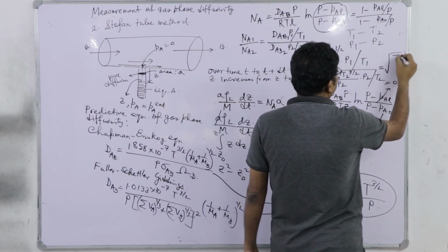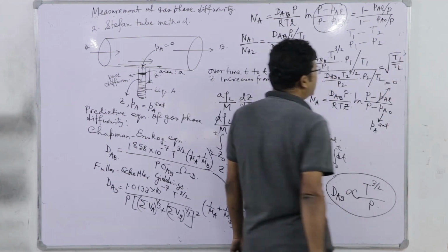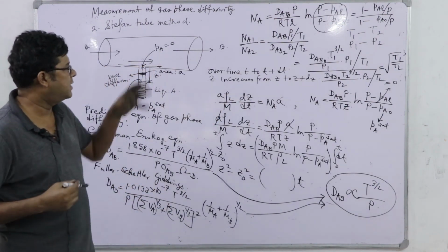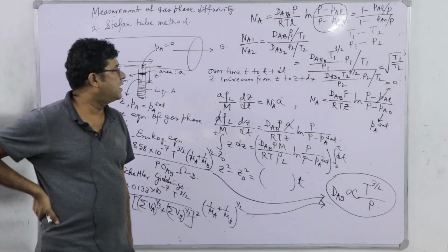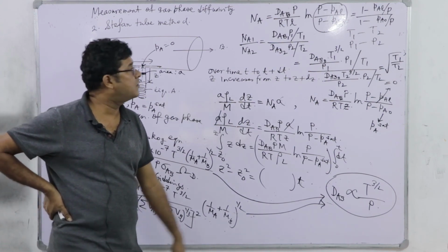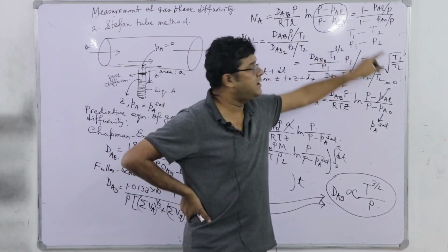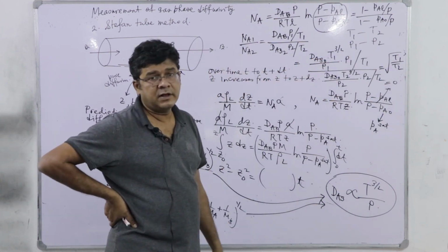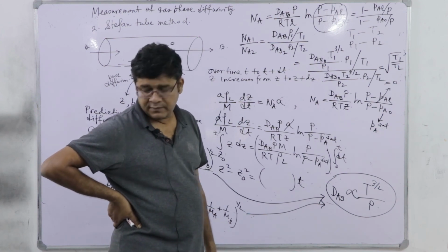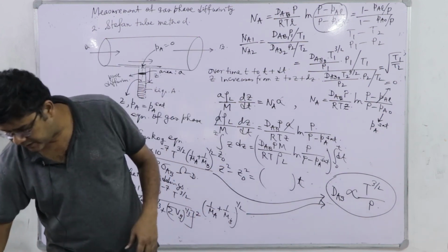So, it is finally giving you T1 divided by T2 under root. So, from this you have to calculate the ratio of these two fluxes where we have changed the temperature and pressure. So, what is important to note is that it is independent of pressure, right. So, similarly you can check it out in case of equimolar counter diffusion. So, that is about the gas phase diffusion.